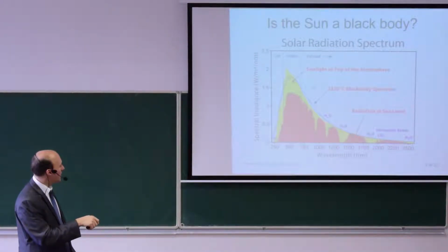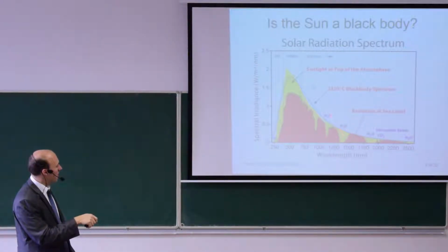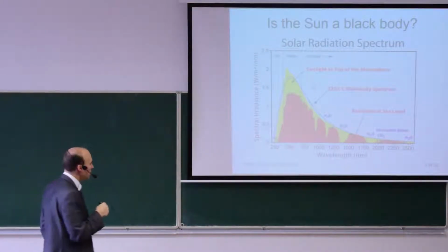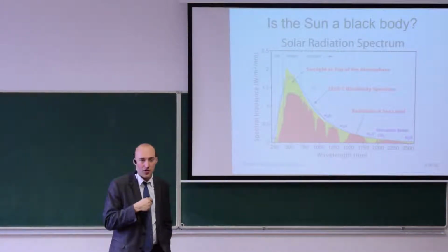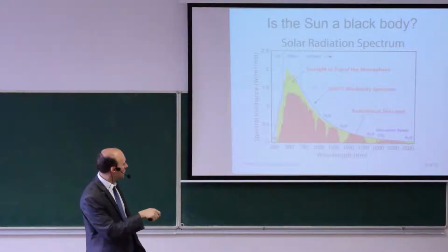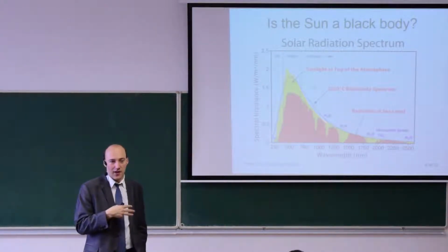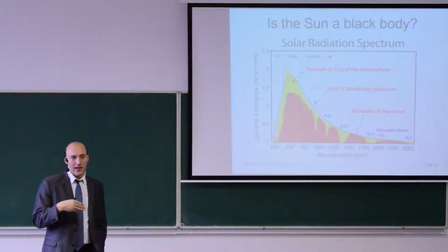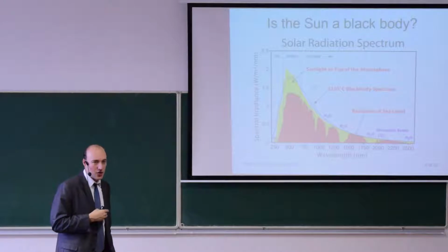So for example, here you see that those parts are absorbed by the water vapor. So if I choose a detector that will measure the intensity of radiation on this wavelength, I will not receive anything, and therefore I will not be able to measure correctly the emitted radiation.